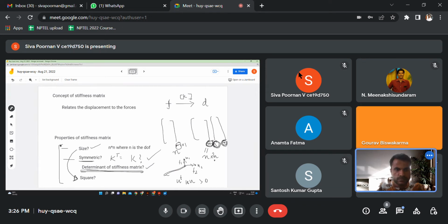Now my question is that even after imposing the boundary condition, you impose it in either the U vector or the P vector. Now the stiffness matrix physically remains unchanged, and only after taking a reduced form of the stiffness matrix are we able to solve it. So how can we say that the global stiffness matrix after imposing boundary conditions becomes invertible?